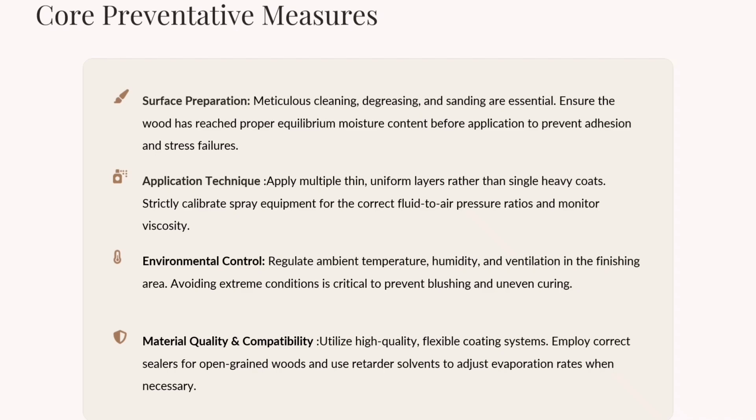Third, environmental control is important. Temperature, humidity, and ventilation must be maintained to avoid uneven curing and finishing defects. Finally, using good quality and compatible materials improves durability and overall finish quality. These measures help reduce defects and improve the final appearance and performance of the coating.